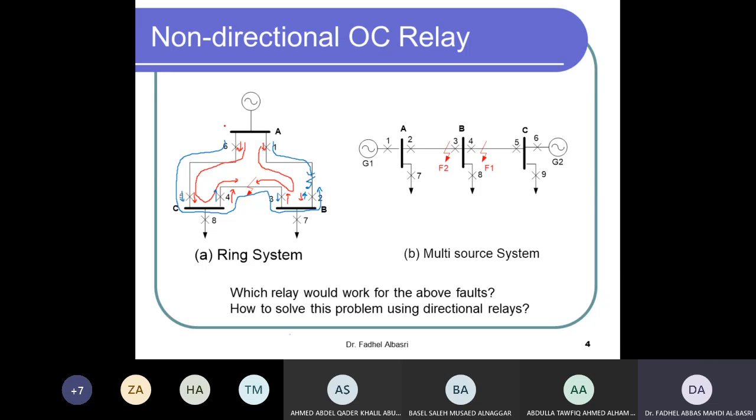supply substation. This could be a primary substation which converts a voltage from, let's say, 66 kV, and it is converted to 11 kV, for example. So these are the main transformers here feeding these substations. Okay, so this is 11 kV.